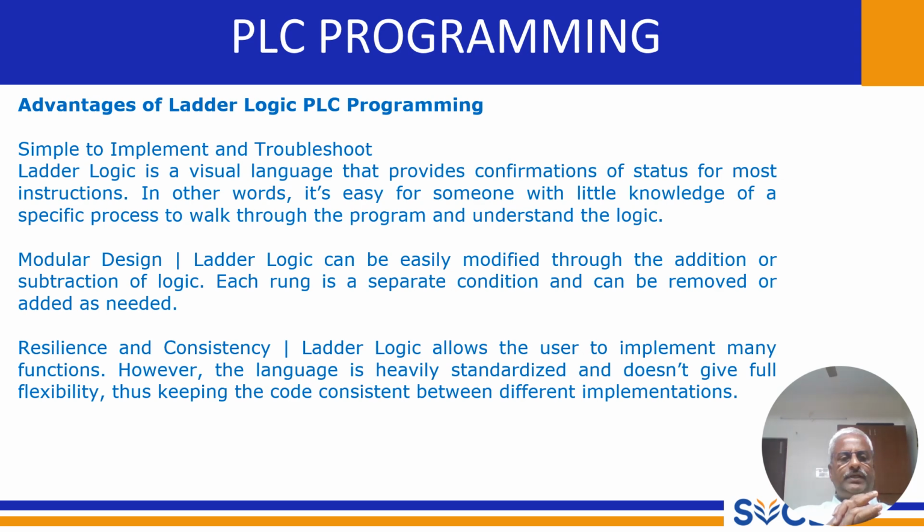Next, modular design. Ladder logic can be easily modified through the addition or subtraction of logic. Each rung is a separate condition and can be removed or added as needed. So what this second paragraph tries to explain is we can easily modify the ladder diagram according to the requirement at any time.